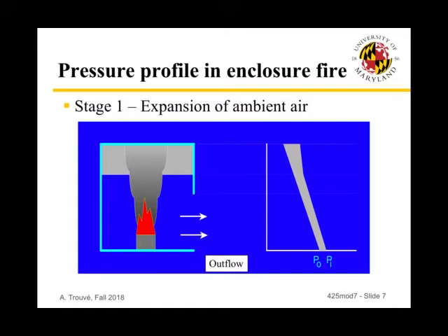And so what you see in these profiles, first, let's look at PO. So we say that the pressure outside is a linear curve because the change in pressure outside, delta PO, will be proportional to the mass density of outside air, rho, times g z.